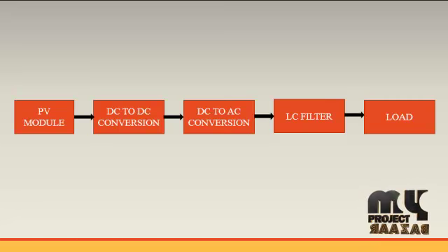The load is considered nonlinear if its impedance changes with the applied voltage. The changing impedance means that the current drawn by the nonlinear load will not be sinusoidal. Even when it is connected to a sinusoidal voltage, these non-sinusoidal currents contain harmonic currents that interact with the impedance of the power distribution system to create voltage distortion that can affect both the distribution system equipment and the load connected to it.